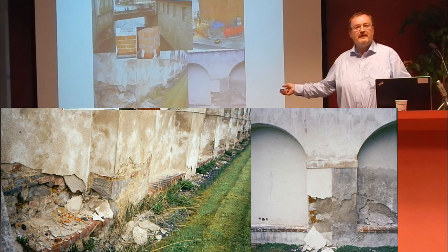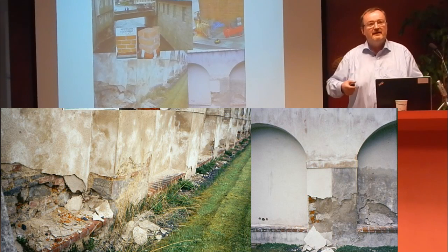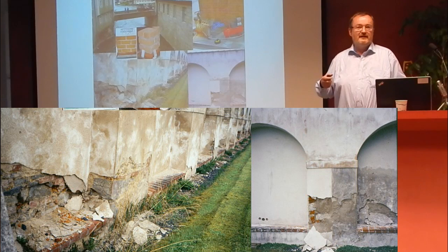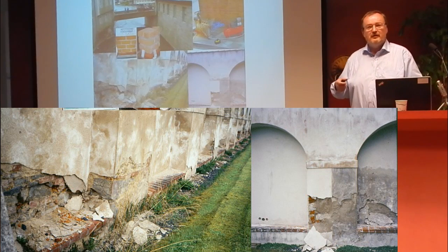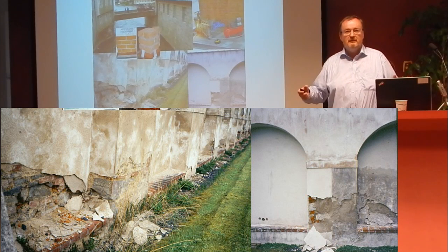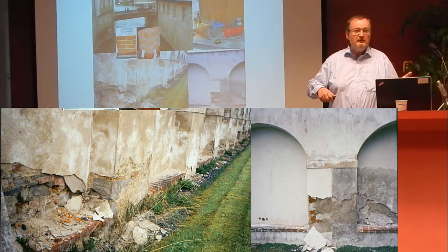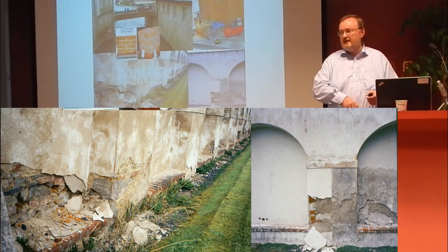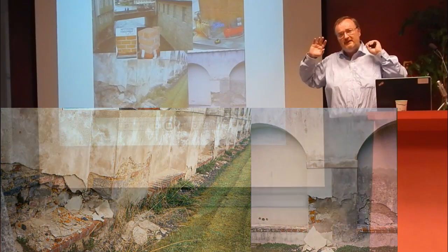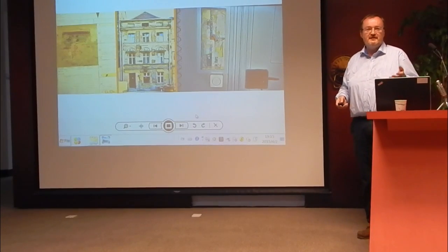So in reality we have salt in the masonry, and the salt will kill the render and will kill the bricks. And all you must do is bring out the salt. So wash it out. The salt is soluble in pure water. So wash it out. And then you can use pure lime water and all is perfect. Not following the industry. That's a principle for better work.